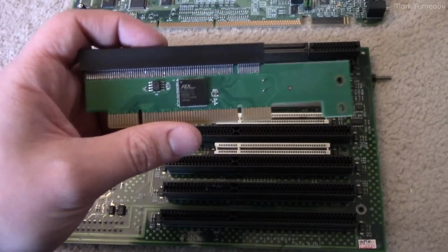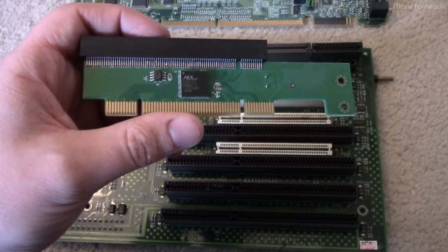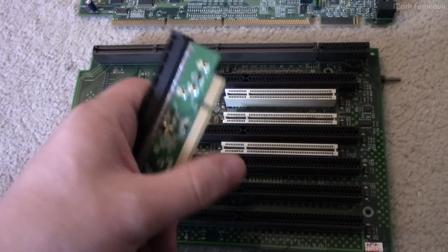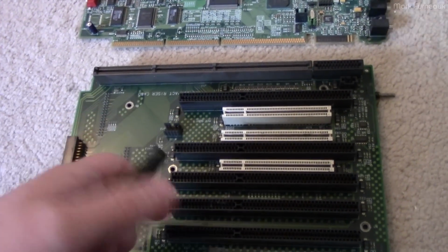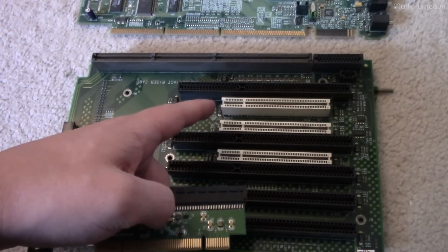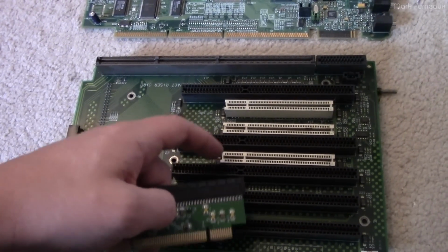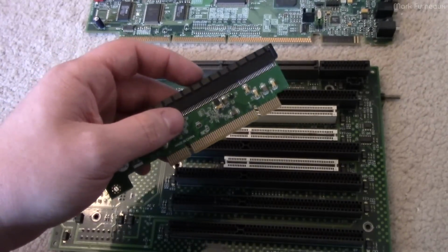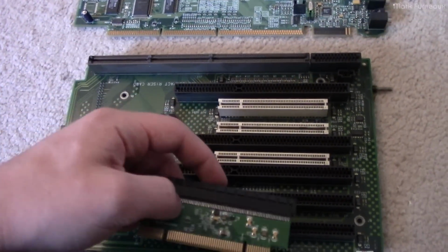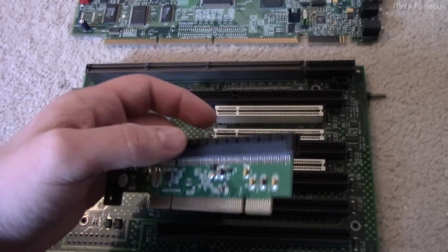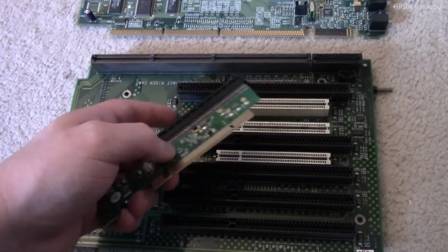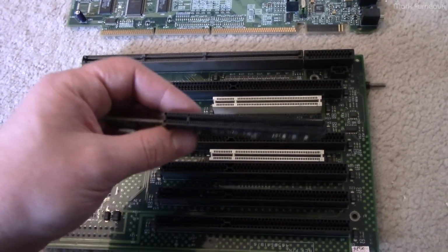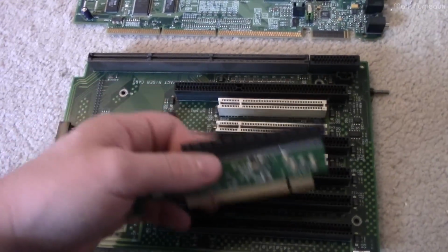Now, there are obviously going to be some limitations. The first one is bandwidth: PCI is significantly slower, and it is a shared bus, so all the slots share the bandwidth, whereas with PCI Express it's usually dedicated. The other thing is interrupts don't work nearly the same way on PCI as on PCI Express. Things like MSI-X interrupts don't work, so the device is going to have to downgrade what types of interrupts it can use. And depending on how the driver was written, it may or may not work properly at all. So from an electrical perspective, it works, but from a software perspective, it's up to the driver.